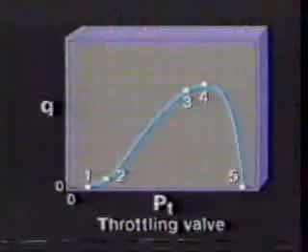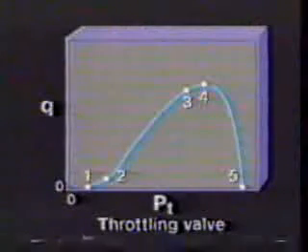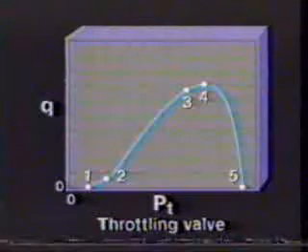As the tubing pressure decreases, the ball is allowed to move deeper into the tapered seat, restricting the flow rate through the valve and making the valve pass less gas. This response to changes in tubing pressure allows the valve to be partially open or fully open as a function of the tubing pressure only. Now let's look at a plot of flow rate versus tubing pressure. It will help us understand the performance characteristics of a throttling valve.